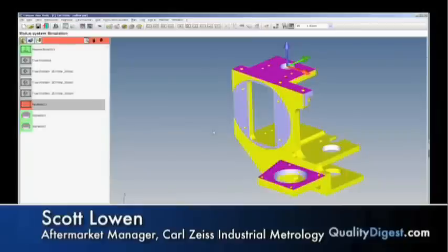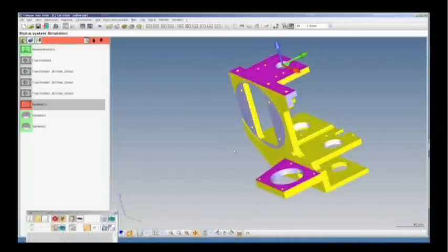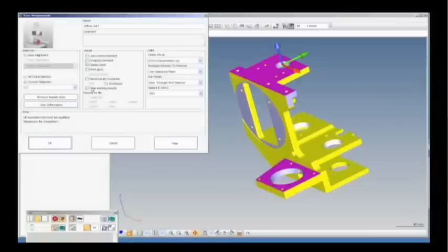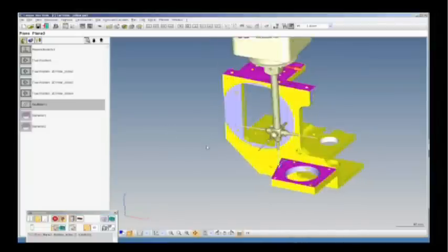Okay. And so we can take it over there, or is there any other steps? Well, there might be one last step here. We can actually highlight some of these and start simulating some of the geometry. Okay. So if I want to simulate this parallelism or perpendicularity, you would just highlight it, or the entire thing if you really wanted to. But I might highlight a particular characteristic that I want to report, and accepting that, it's going to come down here and measure the actual part.